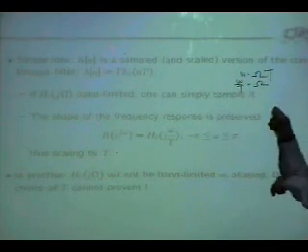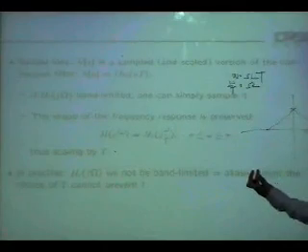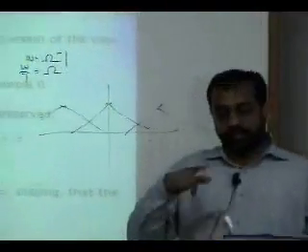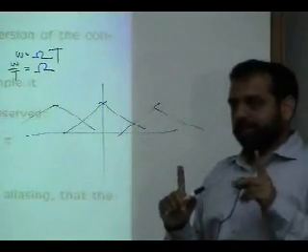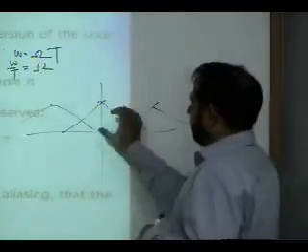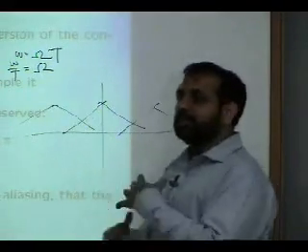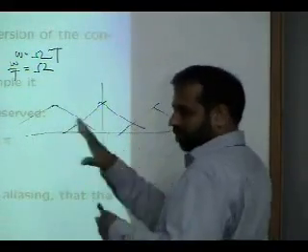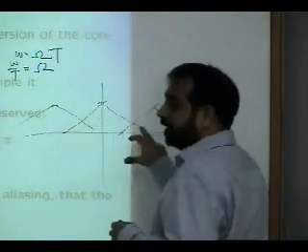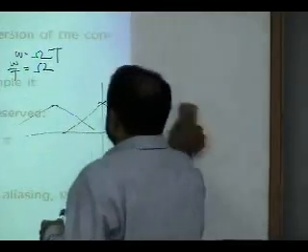Once you do, you make copies, but it is important that it should be band limited. If it is not band limited, then the same thing will happen: aliasing. So this is the problem with the impulse invariance technique, that mathematically it will alias. Maybe your analog filter will be meeting all the specs, but once you discretize it, it may or may not meet specs. I'll show you that because of the aliasing effect, it may not meet specs. So this is a problem with the impulse invariance method.